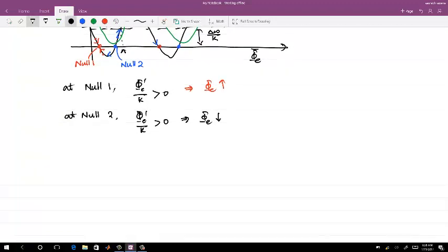So all these things are categorized in different metrics. So let me just say range metrics for PLL. The first one, we will define all these things because this will be defined for other PLLs also. So the first one is called the hold-in range, which is defined as the range of frequencies to which the PLL can hold in lock condition, in a steady state condition.